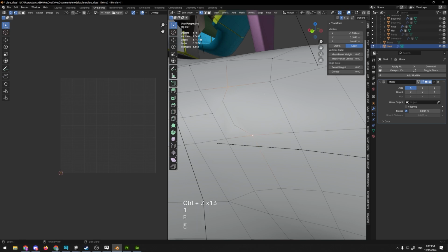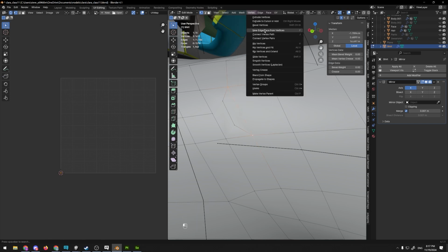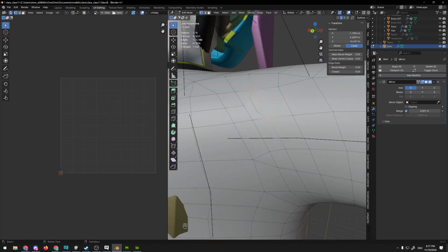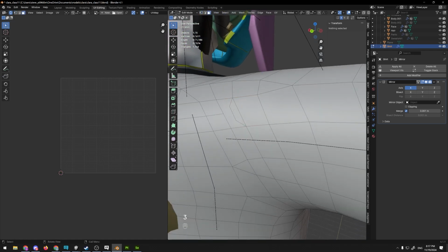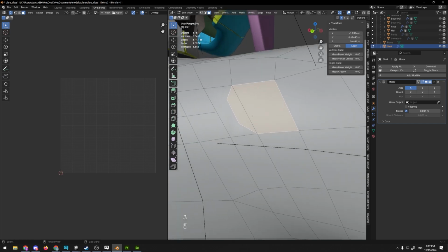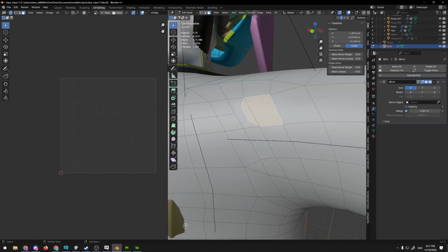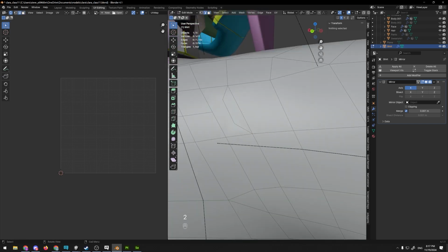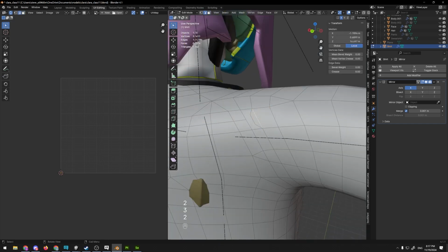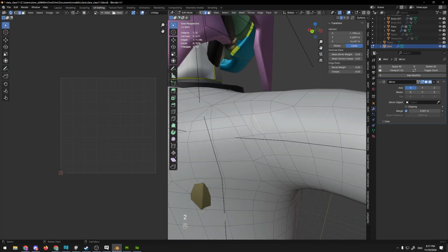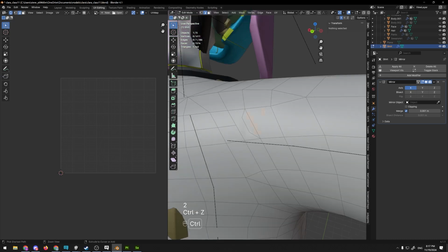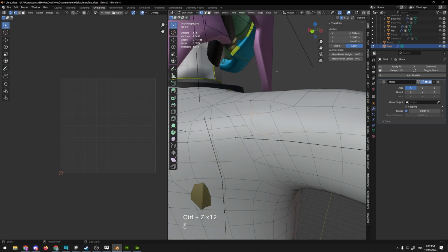You can do something similar with F, which I think is fill. I think that's what that stands for. Maybe. New edge slash face from vertices. We're going to call it fill. I don't know. That looks like it would work really well and doesn't. The reason why is it does not divide out your mesh. You now look like you have an edge here that divides out this poly, and you don't. And that's a problem. And that bites me very often. So be careful when you're using J. F versus J. You typically want to be joining with J instead of using F.